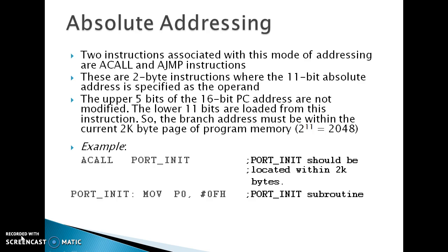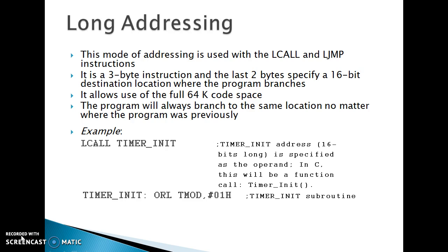Example, ACALL PORT_INIT. PORT_INIT should be located within the same 2K block. PORT_INIT: MOV P0, #0FFH. So here ACALL represents the absolute addressing. Long addressing. The long addressing mode is used with the long call and the long jump instructions.